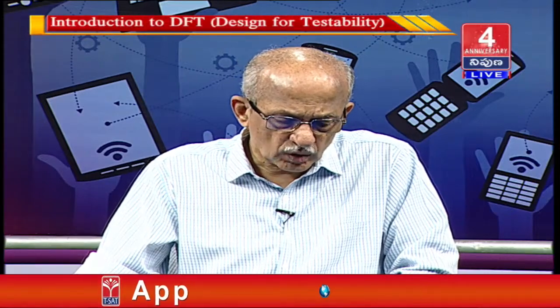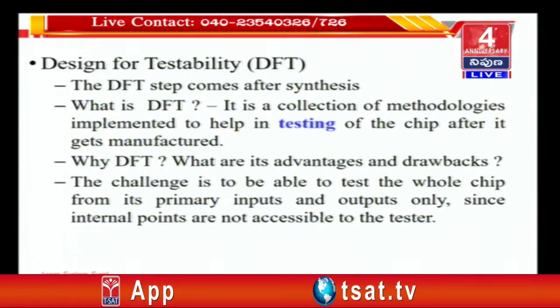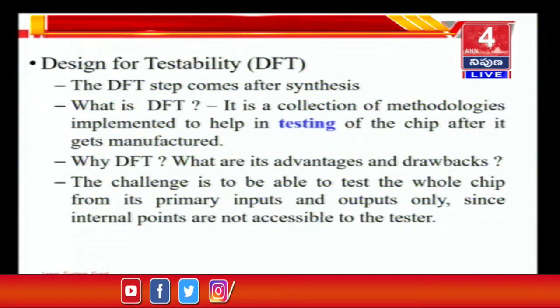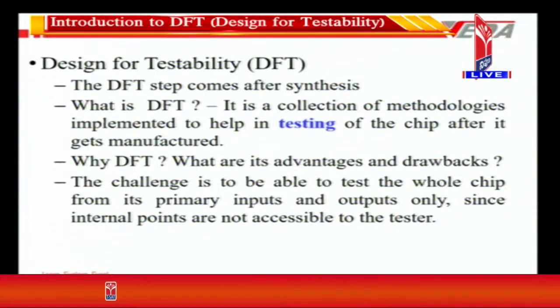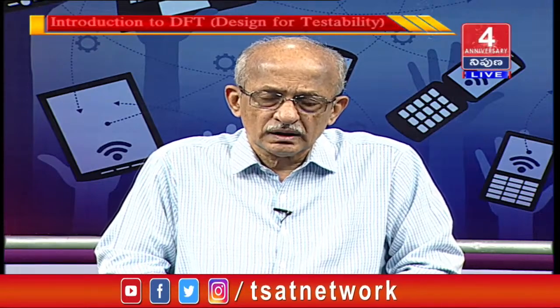So, what are the advantages? The advantages are that it provides a real measure to say that this chip has been manufactured in a quality way. There is some metric, some measure of quality, provided by DFT. Two chips can be compared, and we can say this chip is of better quality than that chip, basically because this chip has done its DFT to a much larger extent than the other chip. Doing a DFT to a larger extent means covering more areas to find out whether any fault is there or not.